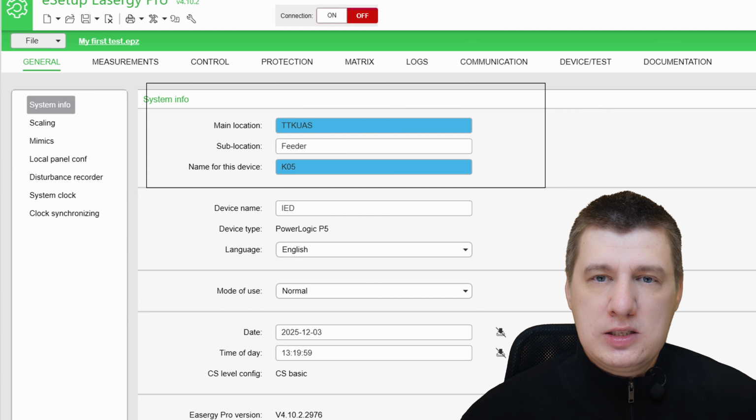The sublocation field accepts text strings up to 20 characters. It can be modified using the setup software or through the HMI panel. This is a descriptive field intended for identification and management. Changing it doesn't affect the relay's protective logic or require a device reboot. If the main location is a street name on a delivery address, then the sublocation is a flat or apartment number. It tells the delivery driver, or the maintenance engineer, exactly which specific door to knock on in a large building.